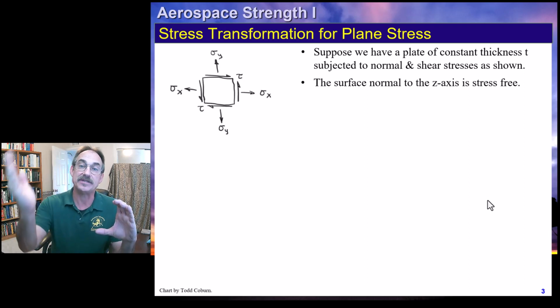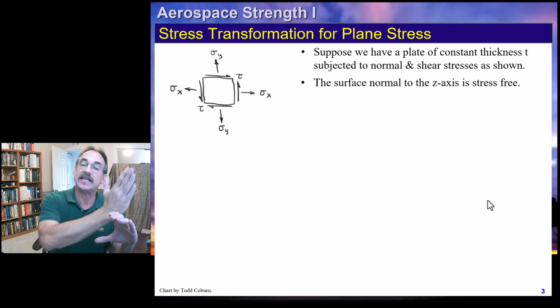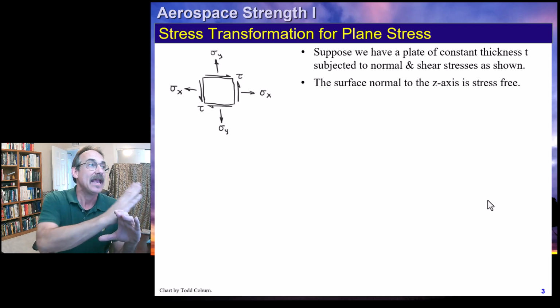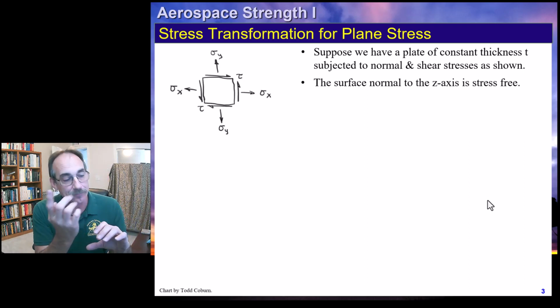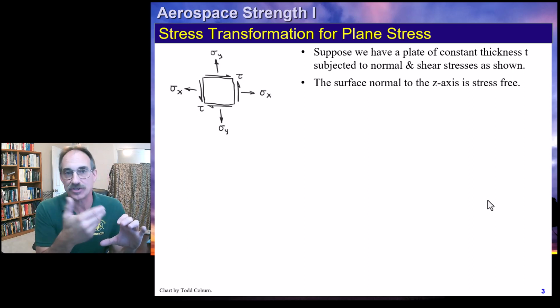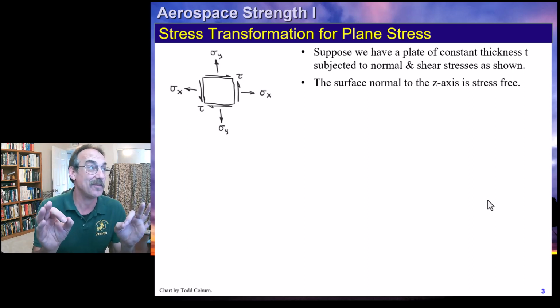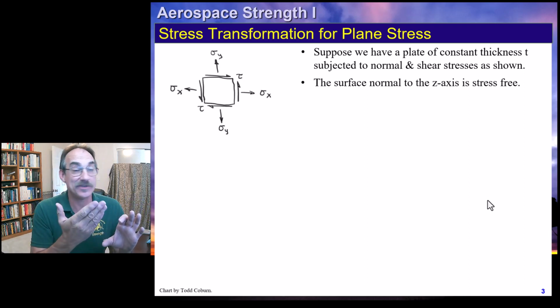On the other hand, it's balanced on the negative face, the face that's cut facing in a negative x direction, and the stress in that direction is aimed in a negative direction. So we have a negative face, negative stress, which is also a positive stress, a tensile stress. They say two wrongs don't make a right, but two negatives do make a positive.